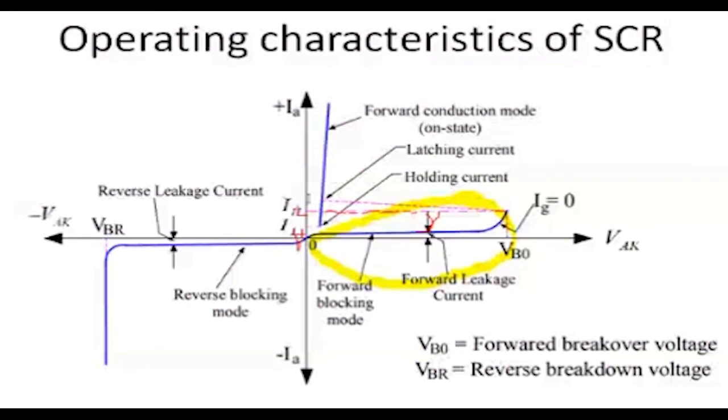Now, when I gave the gate voltage, the J2 wall will not vanish at a time. It will vanish slowly. It will first vanish at the point very close to the gate, and later it will keep expanding. The conduction region will expand. Initially a small space is provided, later the conduction space will increase, and finally it will spread over the entire region so that there is nothing to block the flow of current.